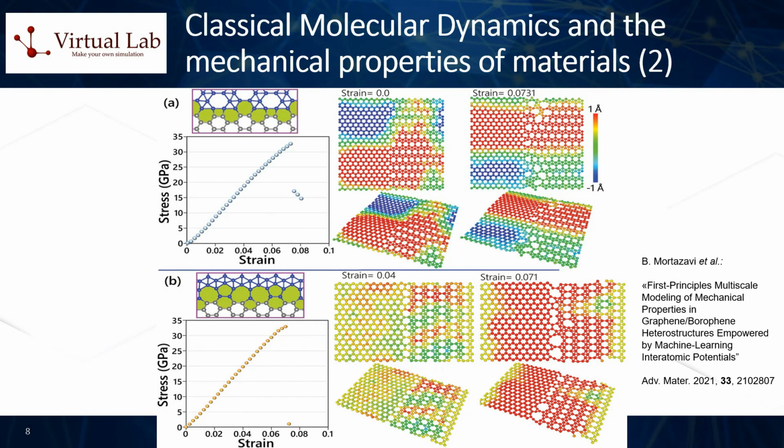The forces between atoms are usually calculated using potential energy functions, which can either be derived from physical laws or fitted to experimental data. While MD provides a detailed, atomic-level view of a material's behavior, there are some limitations. MD simulations can typically only model a small number of atoms over a short period of time, and they assume that atoms behave classically, which may not be valid for some quantum mechanical systems. However, despite these limitations, MD remains a powerful tool for studying the mechanical properties of materials.